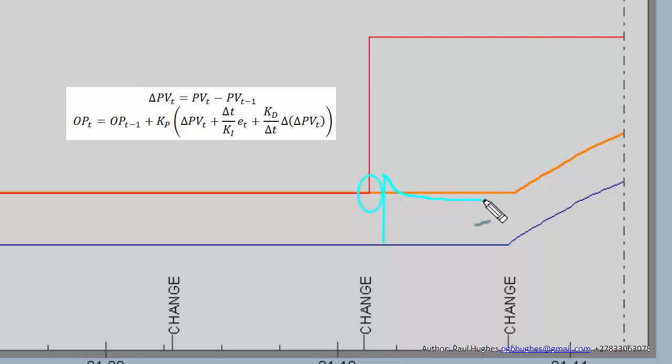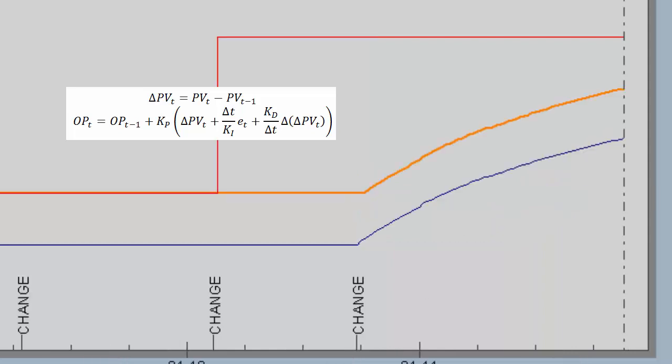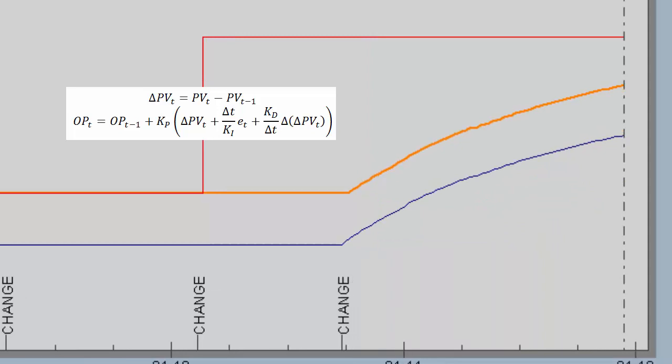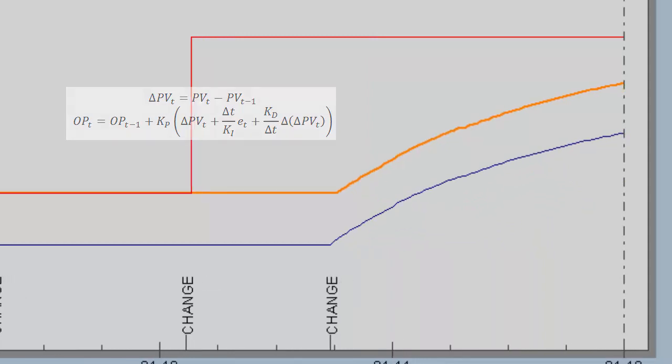It was proportional action, but here we don't see that because the error term is not being used, the PV term is being used, and the PV for this particular area is constant. So you can see it's a constant, and the system slowly goes back to where the set point is. You can see it's not catching up. Eventually it just takes a while. So that's an I-PD algorithm.